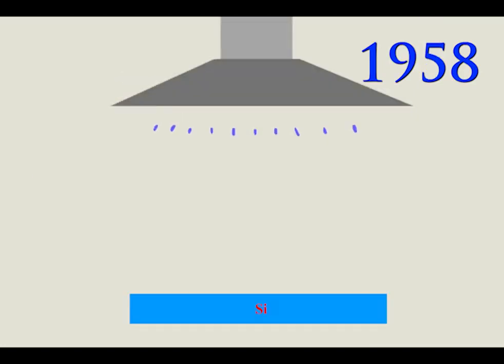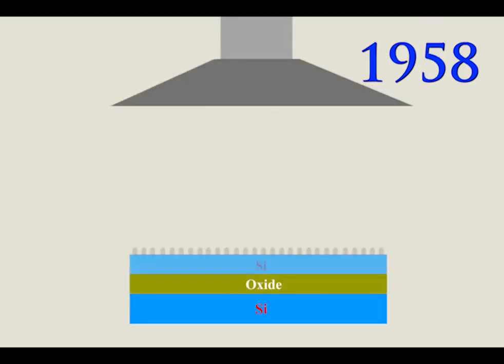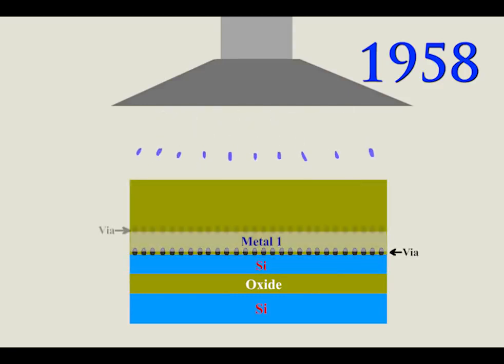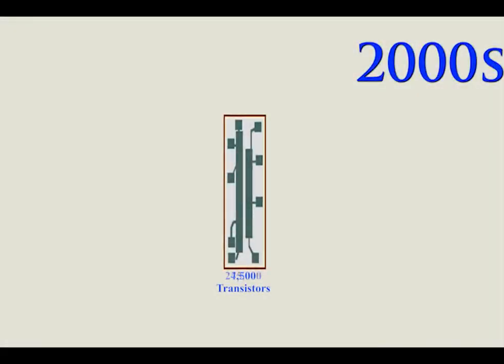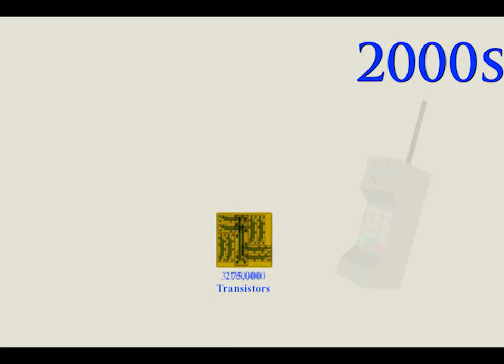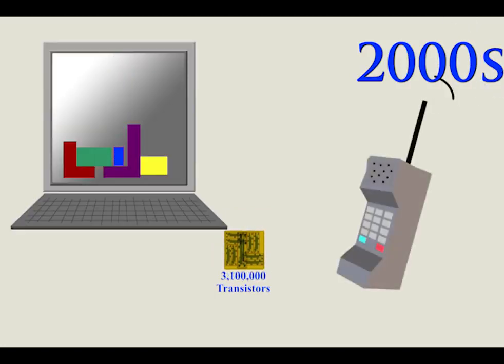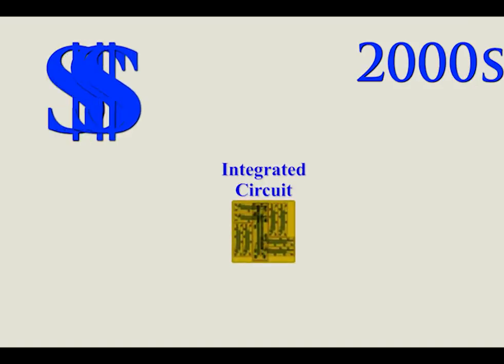The IC is made up of layers of silicon oxide and metal layers to connect the components through masking on a wafer rather than relying on discrete components. As the technology advances, the IC chips get smaller, but still perform advanced complex logical operations fast, while consuming little power. The other advantage of using IC chips is that the cost of the chip is low, since it can be printed layers over layers through automation instead of manually constructing a transistor at a time.